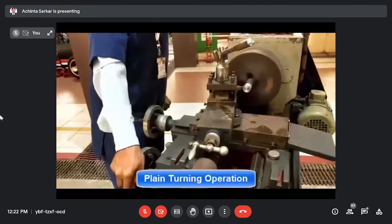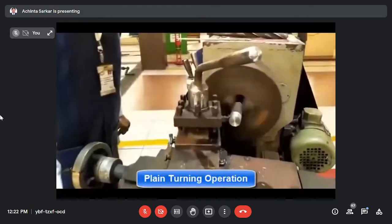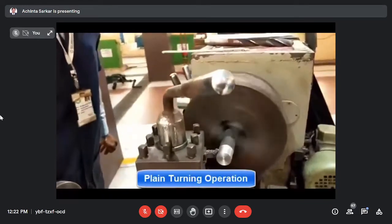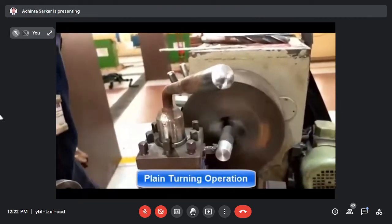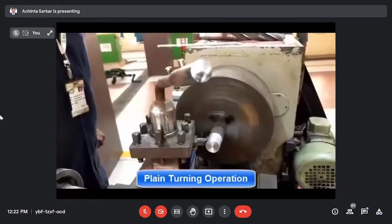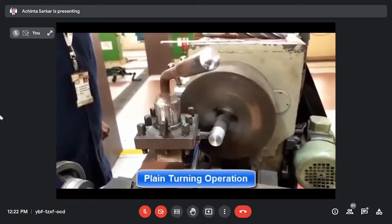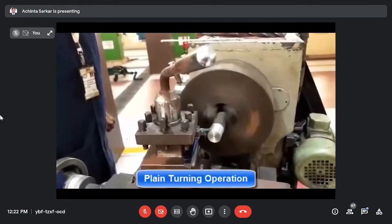Very slowly rotate the carriage wheel towards 30 mm, reducing the diameter of the workpiece, and now we are doing the plain turning operation. By this operation, you get the result of reducing the diameter of the workpiece. That means you can smoothly maintain the diameter of the workpiece according to the required size or dimension.